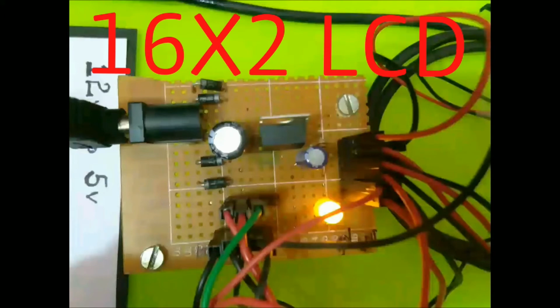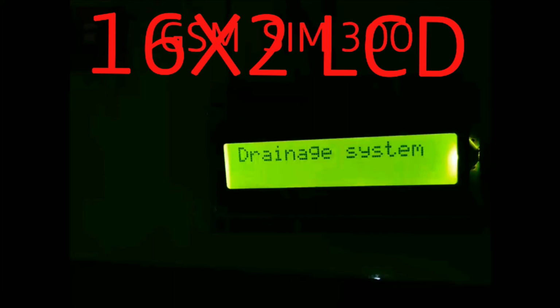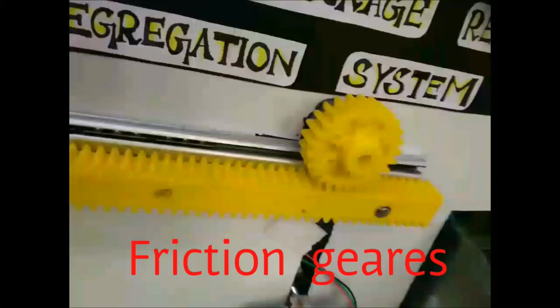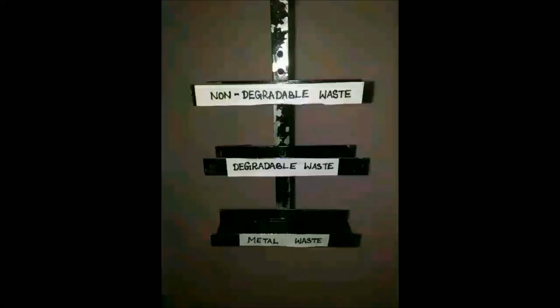A 16 cross 2 LCD displays a message at every action of the microcontroller. GSM SIM 300 module is used to send message to the authorities, and the GSM driver circuit is used to provide 4.3 volts as input to the GSM module. Friction gears are used for swiping and lifting action. A metal plate is used as a wiper blade, and 3 metal baskets are used to collect the segregated waste. A metal plate is used to collect the accumulated waste and lift it up to the segregation unit.